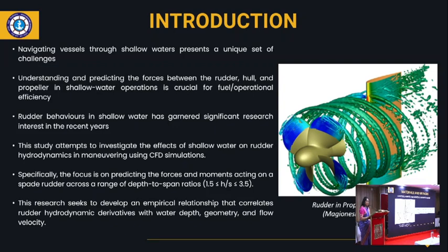And on the other side, we have Y delta. Similarly, we have N_r dot coming, which gets added to the mass moment of inertia, and is supposed to be the added mass moment of inertia. N_v is a coupled derivative in yaw, N_r is the velocity dependent derivative in yaw, and N delta is the rudder moment derivative. So Y delta times delta R gives the rudder force, and N delta times delta R gives the rudder moment.